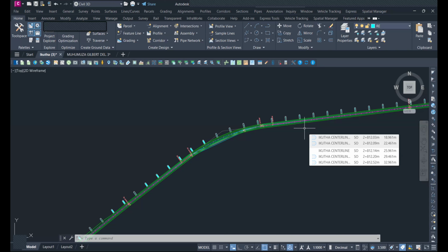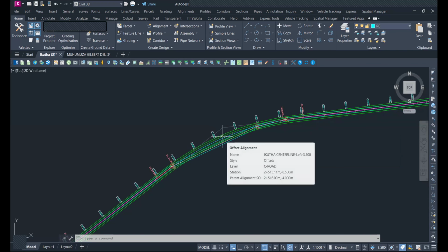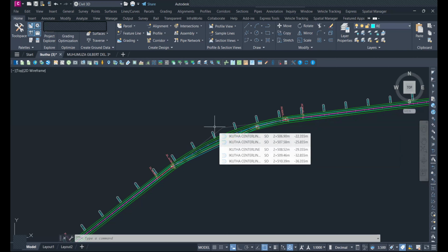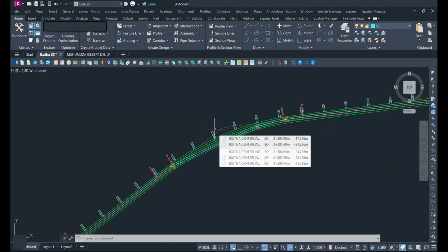No, no. We do widening when the curve is too tight. For example, you see your curves here are very, very large. So let's say we don't have sufficient radius for the curve. There are two scenarios. The first scenario is the kind of vehicles. If you're having a very large truck, you remember the habit of the vehicle, the rear tire of the large trucks tracking inside the curve.